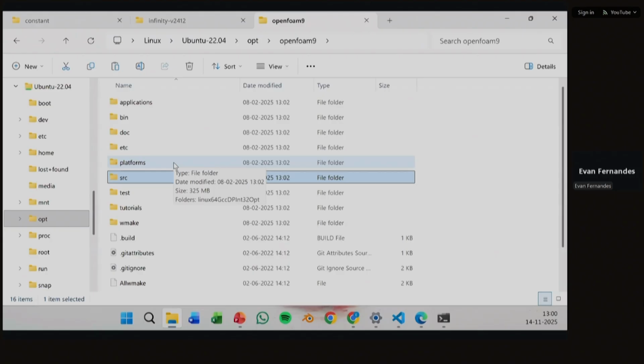So if you type LES and you're using any of the LES models, if you're typing RS and using any of the RS models, those equations are already present in OpenFOAM. Now, if you want to change any of them, if you want to introduce anything custom, you can make your own libraries as well. And you have the GitHub repositories also. They also have a few pre-built custom libraries you can compile. They usually give the instruction sheets of how to compile a library as well.